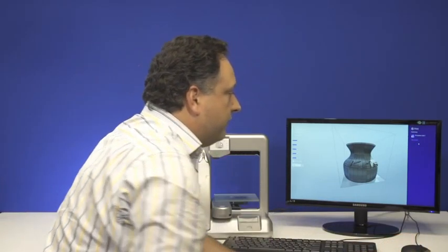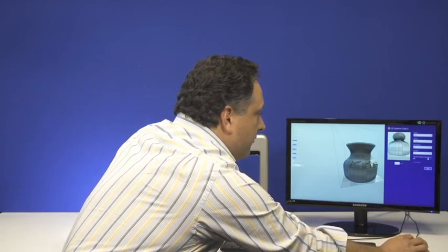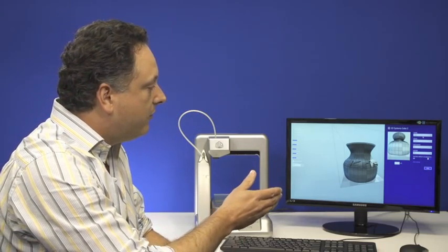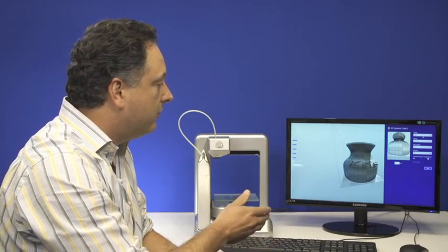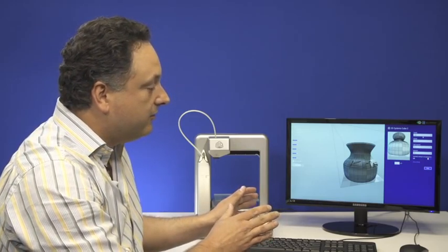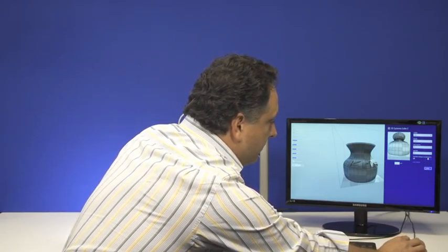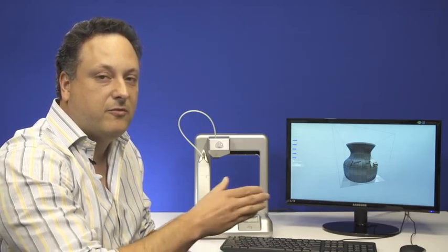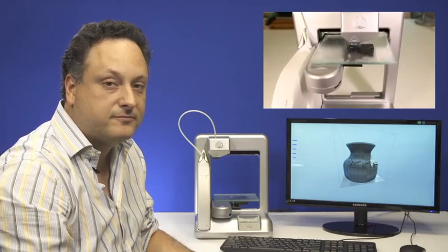And here you see a 3D Systems Cube 2 printer configured, and that's the device I have over here. I'm going to pick that device, and you'll see print settings come up that are specific to the printer. So you see quality, density, whether I should add support material or a raft. I'm just going to use the default settings for this print. And now I'm going to click the print button. At this point, the model is prepared by the application and sent to the print pipeline. And the pipeline will then send that to the printer.